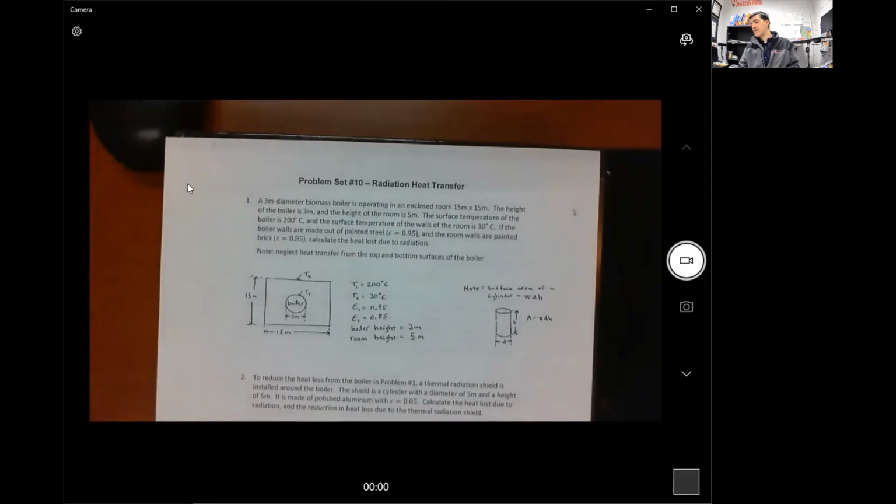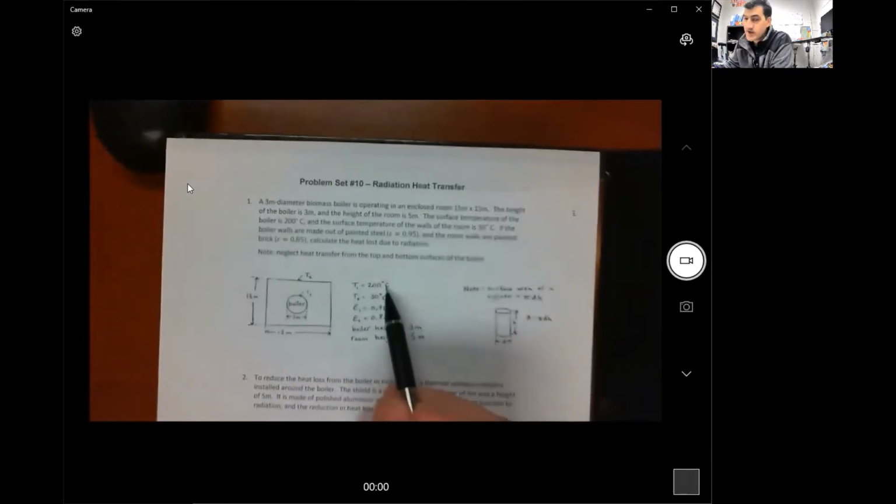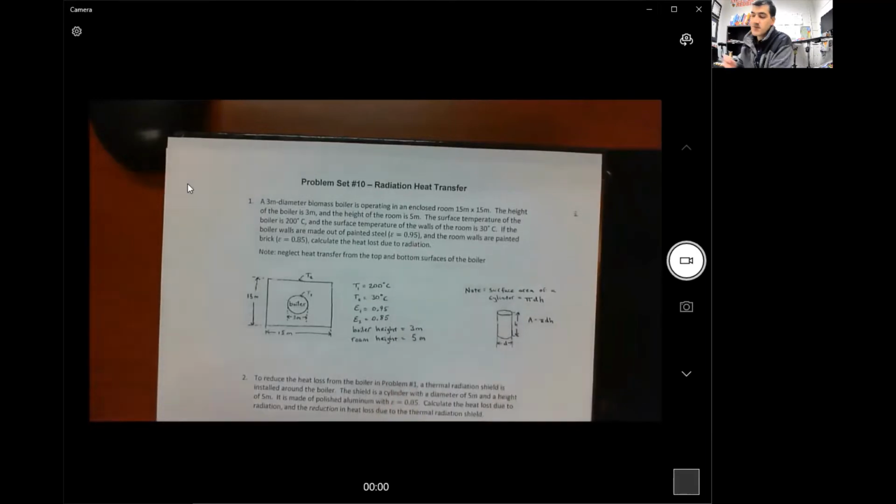And then we can calculate our R rad total by including the Stefan-Boltzmann constant and the temperatures, which we know. But do note that these temperatures are given in Celsius, which is probably most common to measure temperatures in, either Celsius or Fahrenheit. But remember that when we plug our temperatures in, they must be in Kelvin, or else the formula's not going to work. So you've got to have these in Kelvin. So we'll do that.